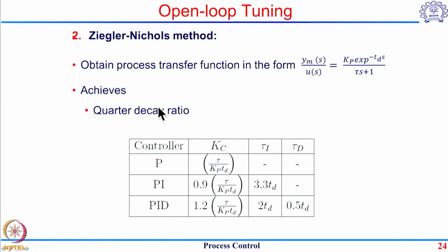So these are the two commonly used methods for open loop tuning. Now one of the main disadvantages of open loop tuning is that you are putting a lot of emphasis on the operator to maintain the plant operation when he gives the set point step change into the valve opening. If he gives a much bigger step change into the manipulated input, then the system may drive to a new steady state, or it may go into an unstable region. So a lot of times there is a possibility that you would lose production, as well as you may destabilize or shut down the plant.